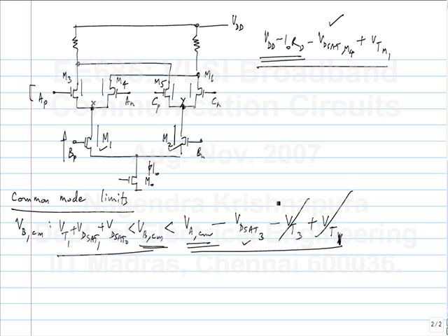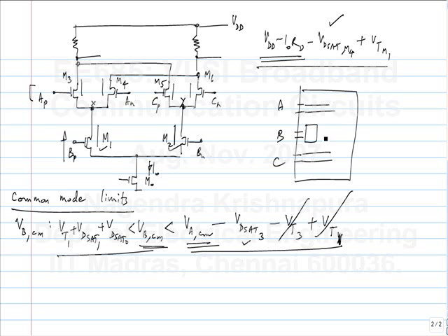Source follower. So we need a level shifter. Let's say we have the circuit where A, B and C come from the same output, meaning some other logic like this. A, B and C are outputs like this. Then A and C can go straight into the circuit. For B we need to have a level shifter.